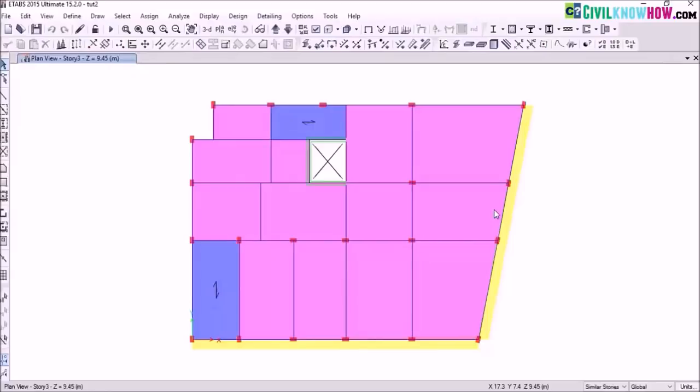In the case of wall load, there are two ways that you can define it in Etabs. One is by using the draw wall option or assigning it as a uniformly distributed load on the desired frame line. But here I prefer the second option because you can assign the desired wall load as UDL and it is a much more flexible option.